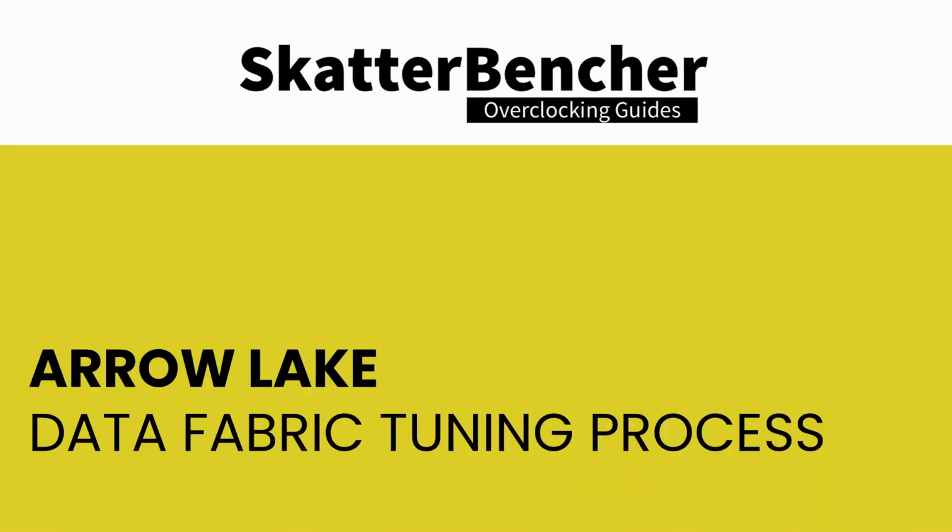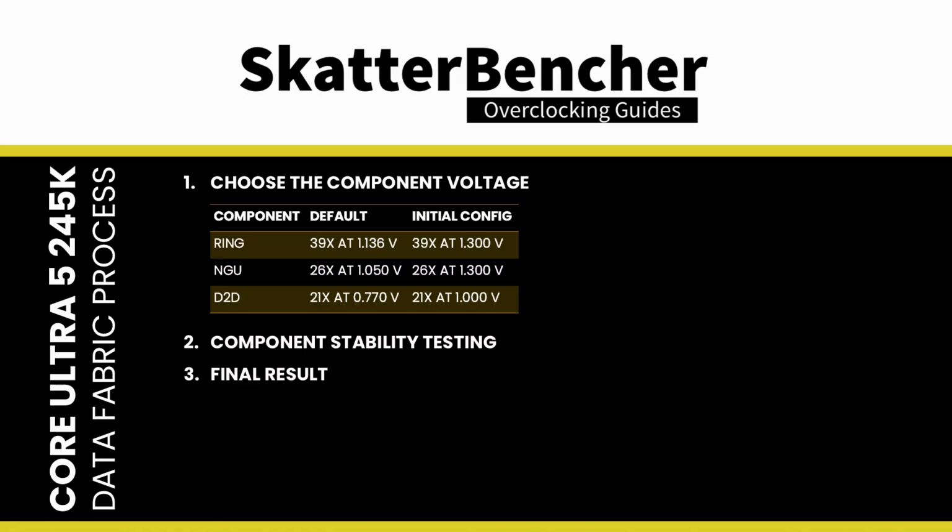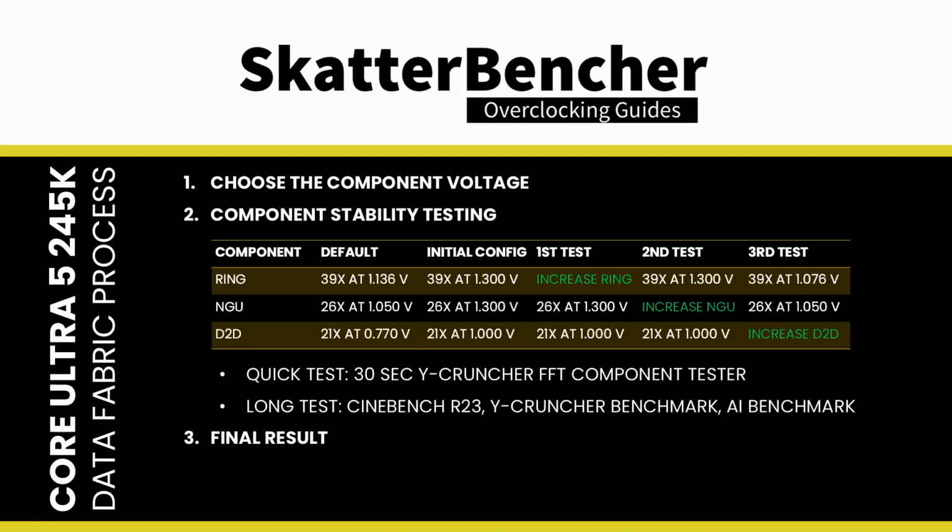Tuning the data fabric is a matter of going through every component systematically. I suggest that you first pick target voltages for each of the components, set those in the BIOS with the default frequencies, and then increase the frequency one by one, trying to figure out the maximum stable frequency. The initial test can be very quick. For example, I'll run a 30-second cycle of Y-Cruncher FFT component tester to find the initial upper limit for each component. When I know the upper limit, I'll set all target ratios and do longer stints of stability testing, including the introduction of other tests.